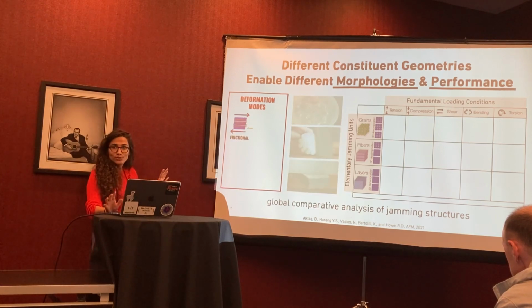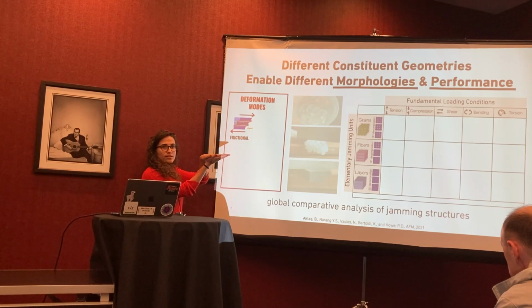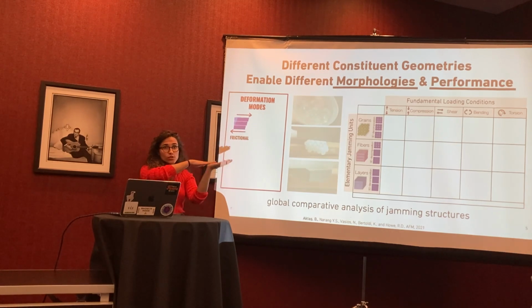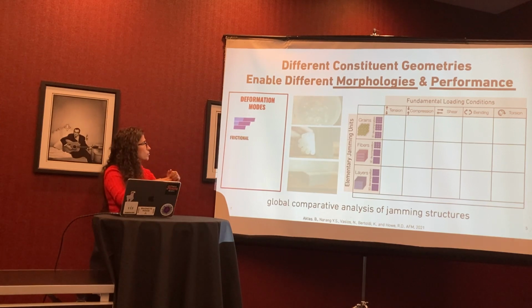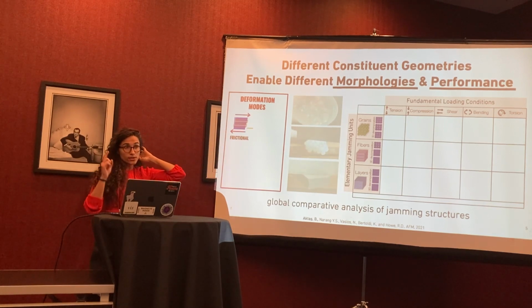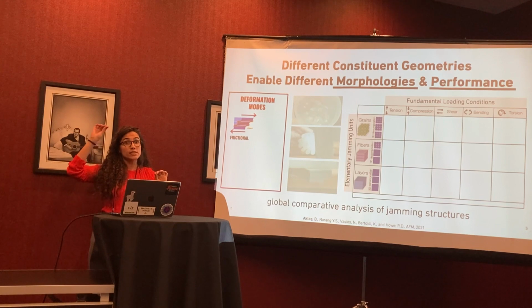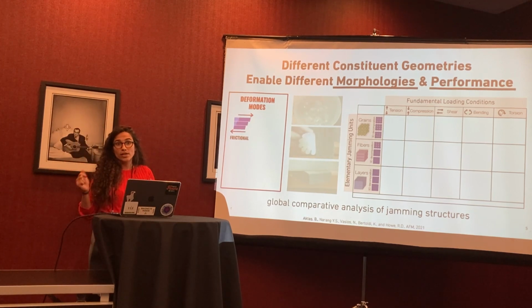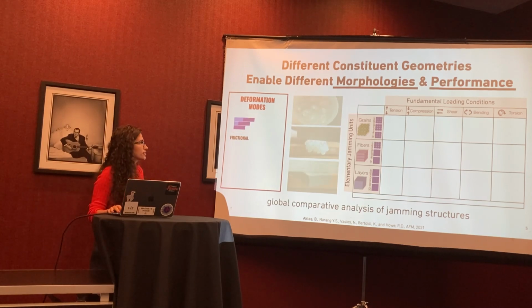The first one, I already introduced this before. Things are locked until a frictional threshold is exceeded, and then they start sliding. So this could happen in bending structures or things like friction clutches, for example. This kind of behavior exists here. And here, the thing I showed, that you have this really nice, clean, elastic regime, and you can change at what point you're transitioning to the plastic regime. So this could be quite advantageous.